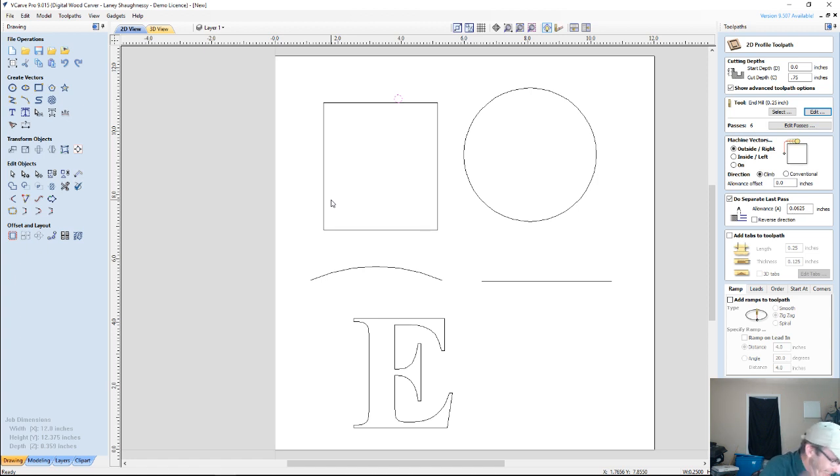We want it straight, 90 degrees. So you always want to make sure that your bit is running at a right angle, or square, to the material. But those witness lines will be eliminated because it's going to cut at a distance away from the material all the way around for however many passes.